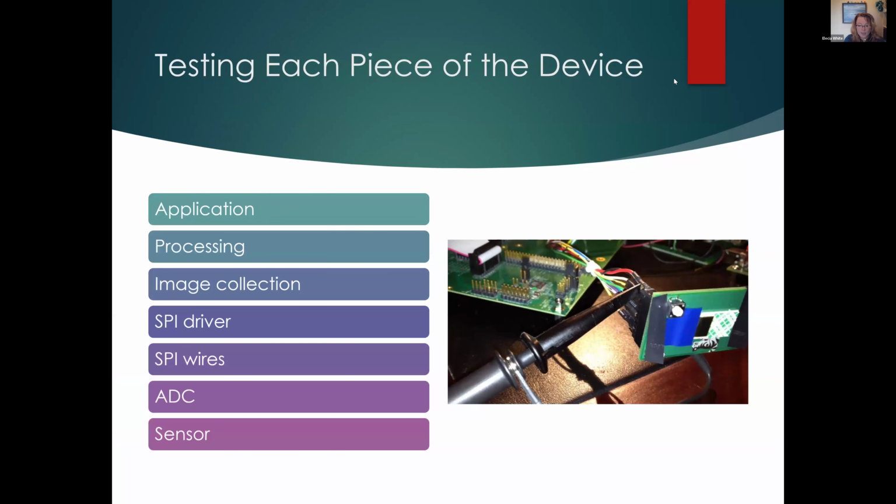And some might say we can decrease our reliance on hardware and printf debugging by doing better software tests. And I agree. That time I mentioned earlier in the schedule when I'm waiting for hardware to finally arrive, that's when I write a lot of hardware bring-up tests. And I like unit tests. And I like breaking up an application so that the algorithm can run on a PC with canned data, so I don't have to work on my hardware all the time.